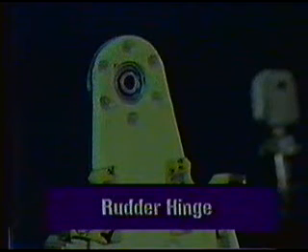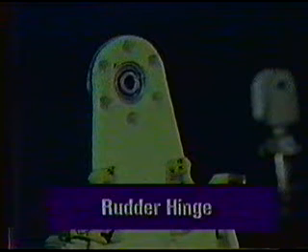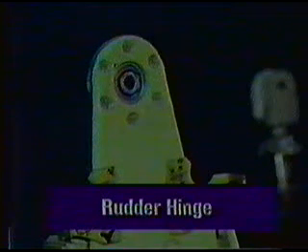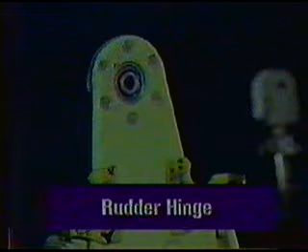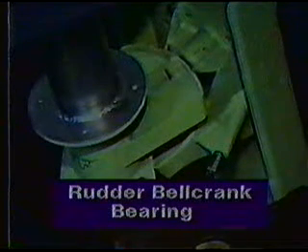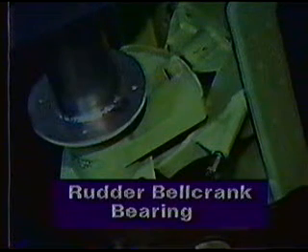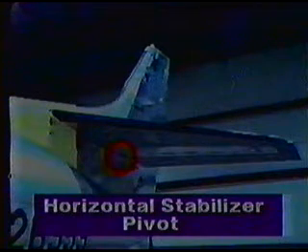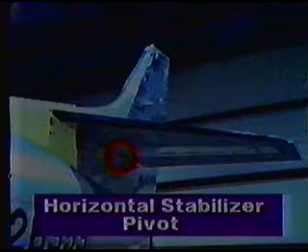Hinges and bearings used in the flight control system include riveted assemblies that are bolted to the wing or stabilizer spar and are referred to by the control surface that they accept, such as rudder hinge or elevator hinge. Because of its design difference, the most inboard elevator hinge point is called the elevator bearing or inboard hinge bearing. The lowermost rudder hinge point is usually referred to as the rudder bell crank bearing. The bearing that the horizontal stabilizer rotates on is called the horizontal stabilizer pivot.